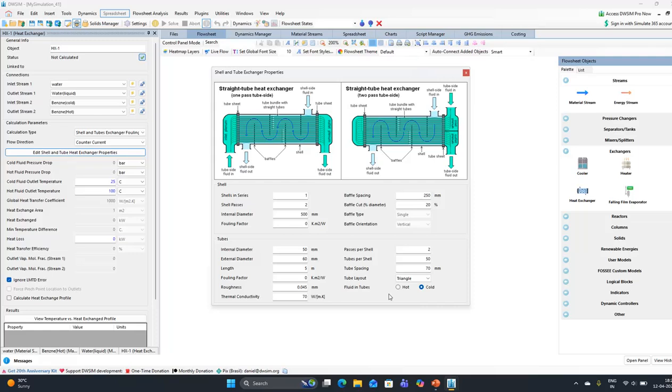So in general what we do in the process, we heat up the process fluids which are sometimes reactive to the metal, so we keep them in a tube so that we only lose the metal when they are reacting with the tubes. Only the fouling of the tubes should happen so that we can clean them using water. If we keep them on the shell side, what will happen, they will foul the tubes as well as the shell, because they are coming in contact with both. So cleaning will not be very nasty in these cases, to clean the tube side from the top, because from here if you pass water at a high pressure, then the tubes will automatically clean.